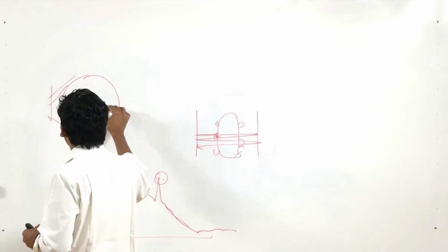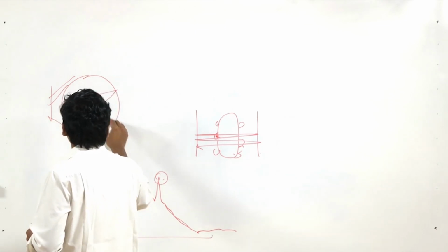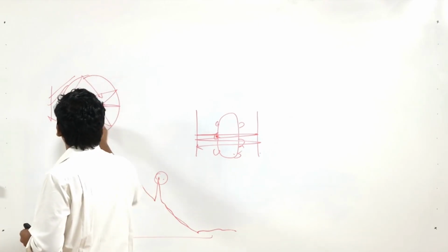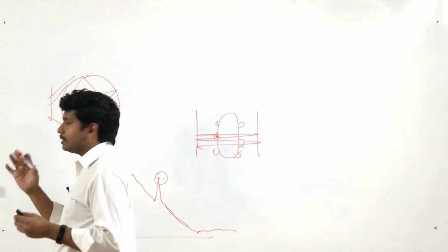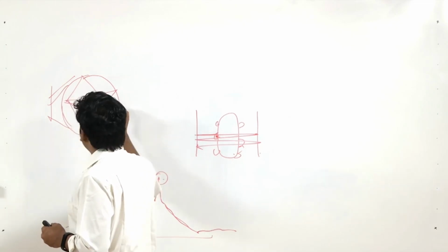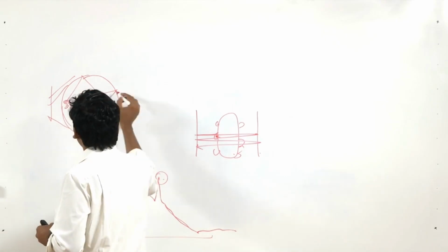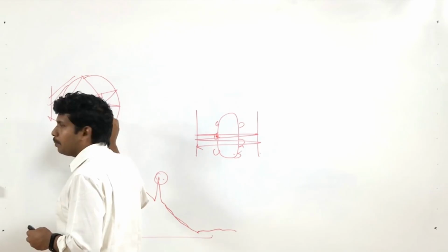If you are seated here, this sound gets reflected and re-reflected from different points. What all these concave surfaces are doing is focusing sound on you if you are sitting here, say receiver 1, and this is the source. Everything is reflecting the sound and channelizing it to one single point.